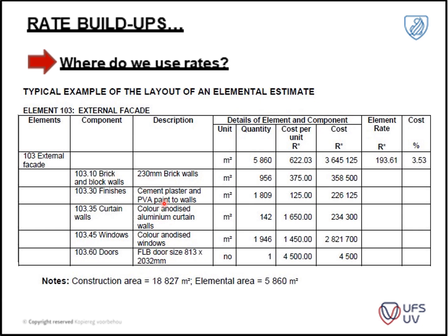Then you will go on like that. In your description, you differentiate between different units and the rate buildups that will be conducted underneath them. Brickwork is measured as a per square meter rate, but you might have an instance where you have to include reinforcing or brick force, which is usually measured in meters, with the size provided for it. You need to calculate how many layers of brickwork there are,